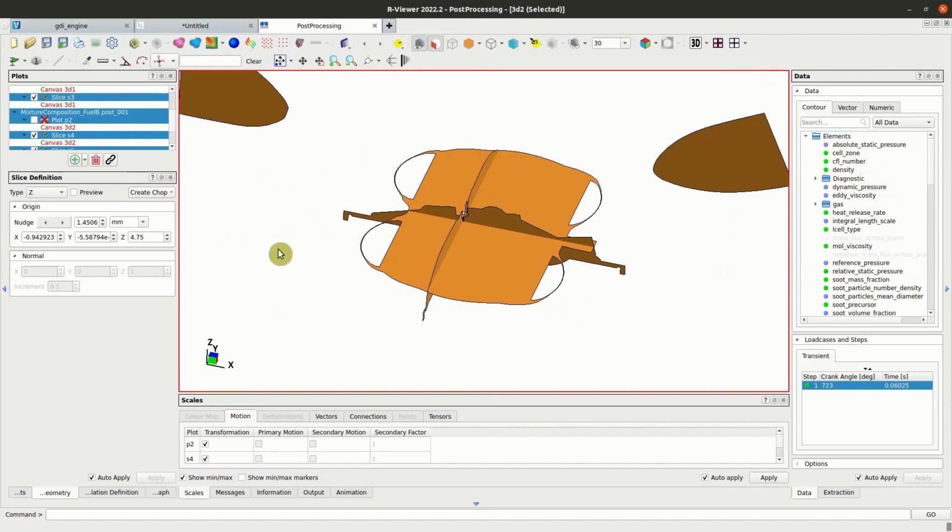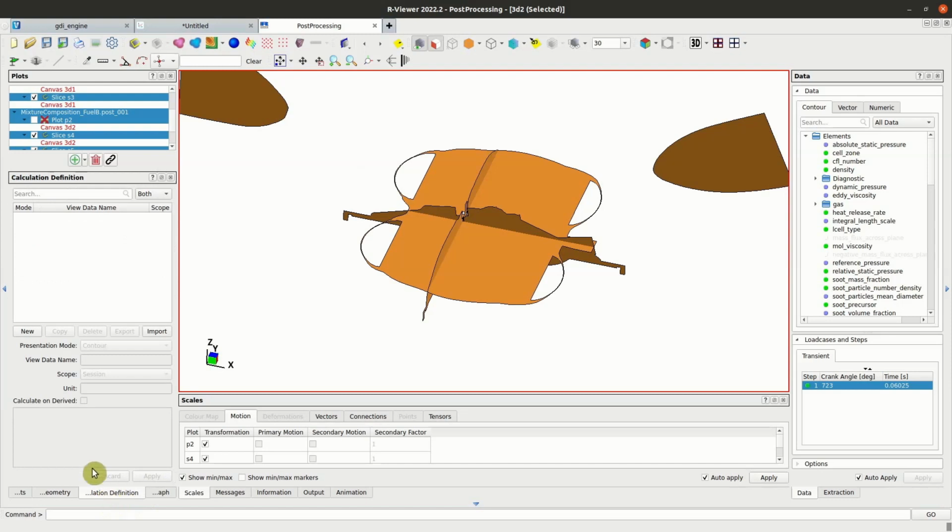We will be looking at the local deviation of the gaseous fuel composition compared to the liquid fuel. For this, let us use a user-defined variable that will evaluate this deviation. We'll start with ethanol, and we will start by normalizing the ethanol mass fraction by the total fuel fraction, and normalize this result by the ethanol fraction in the liquid fuel, which is 0.206.